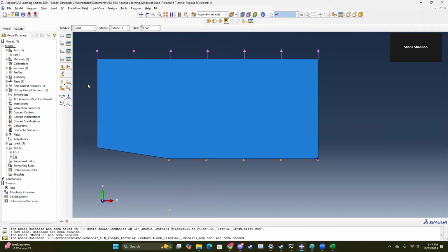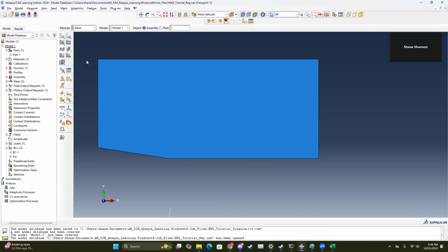The idea is, again, he talks about it in the same lecture, about the 30-minute mark and onward is the whole part of the lecture talking about meshing, is that he wants it really dense around where you're actually trying to see important things. In this case, it would be the crack tip. So we're going to do some things with the mesh to get the element density around here as high as possible.